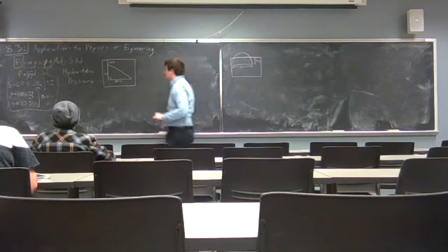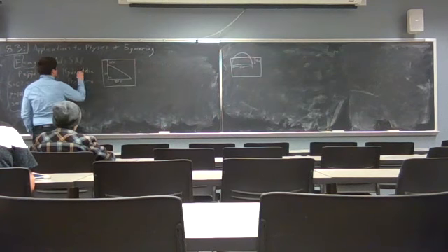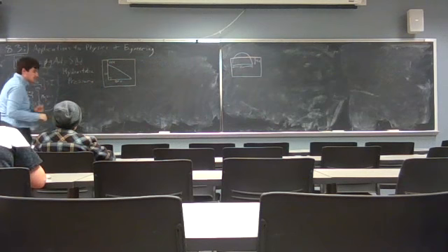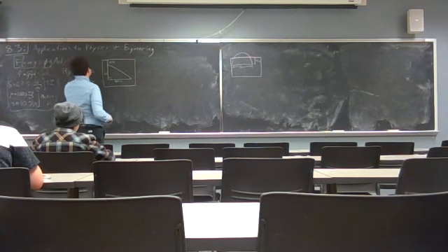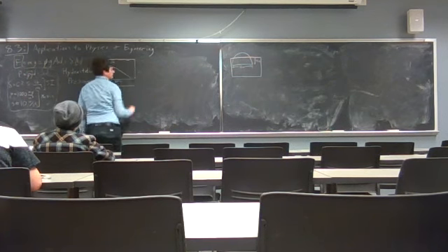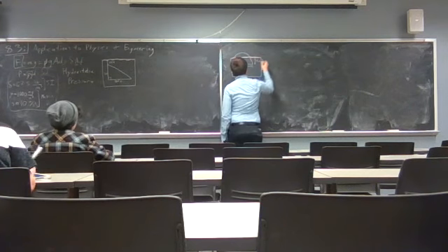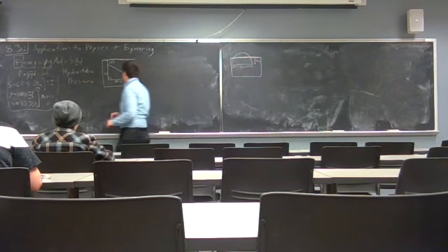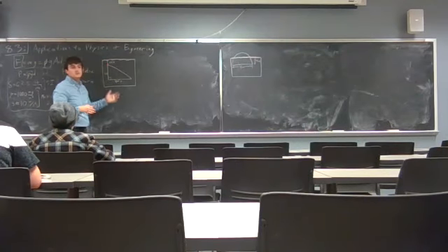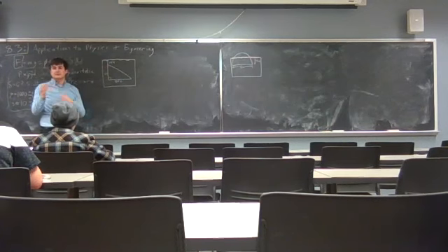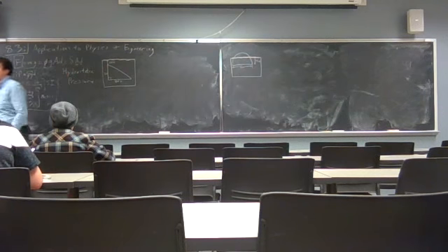Now, the only things that are going to change are the depth and the area, right? The depth won't be too hard to find. We just have to understand, well, where's the surface of the water? In this case, maybe I'll put a little curvy line so we know where it is. That's going to be here, right? And so the depth at this point is 2, for example. The depth down here would be 2 plus 5, which is 7, right? And so we just have to set up some sort of simple linear relationship to know how deep we're going to be.